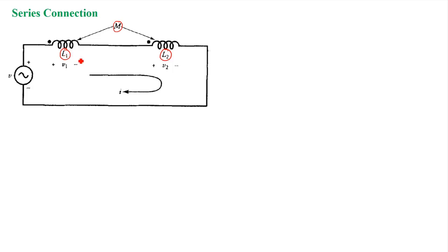and they are in the condition that the magnetic flux is aiding each other. That means when this voltage source is connected to these coils connected in series, and the current passes through these coils, they will produce voltages in such a manner that voltages will be additive in nature. They will not oppose each other, right? So that is why the dot convention is mentioned.